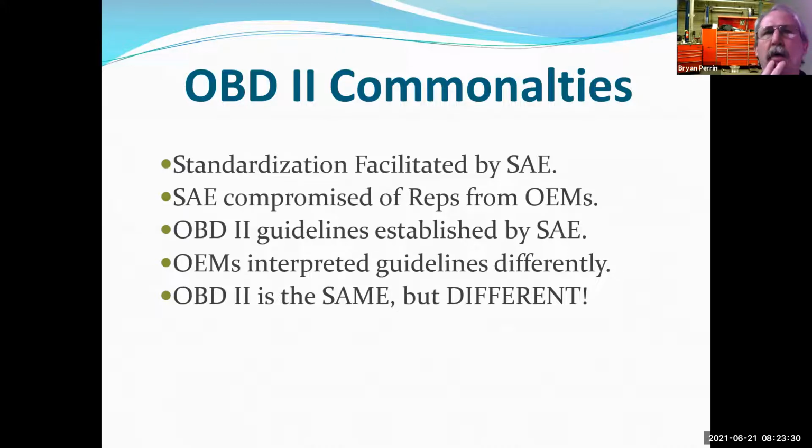In 2010, we introduced permanent codes. These are codes that you can't clear with a scan tool. They don't turn the check engine light on, but you can't clear them with a scan tool. They're designed so that once the car is fixed and the car recognizes it's fixed, it'll clear the permanent code. So it's a tattletale. It's all about emissions enforcement. BMW took permanent to mean it never goes away.